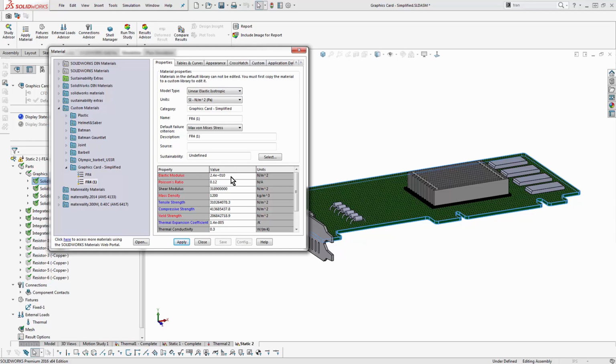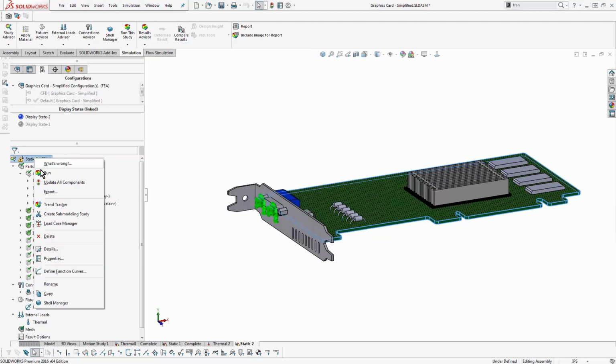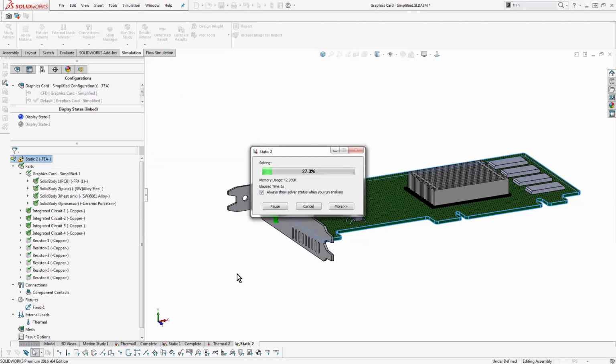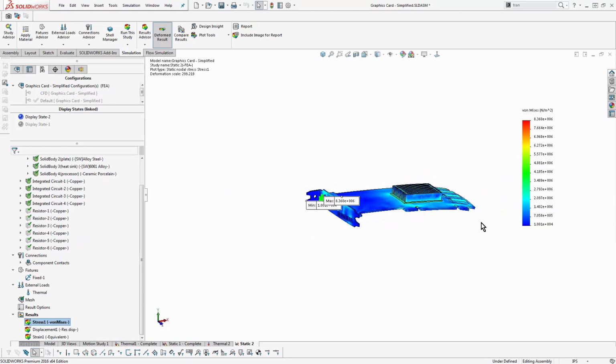So you've got to click on the box, hit the drop down, and hit temperature dependent. That links it to whatever data you input. If you don't do that, it just stays constant. Alright, there we are with some pretty reasonable looking results.